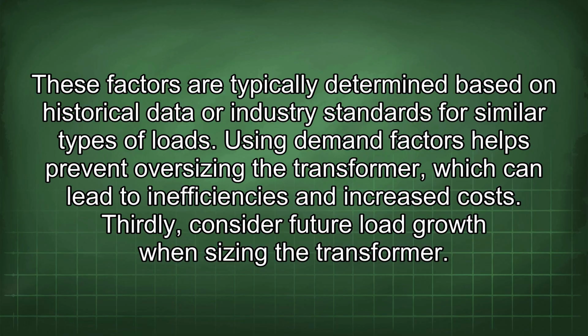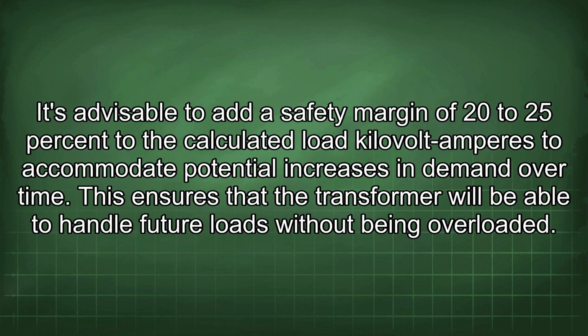Thirdly, consider future load growth when sizing the transformer. It's advisable to add a safety margin of 20 to 25% to the calculated load kilovolt amperes to accommodate potential increases in demand over time. This ensures that the transformer will be able to handle future loads without being overloaded.